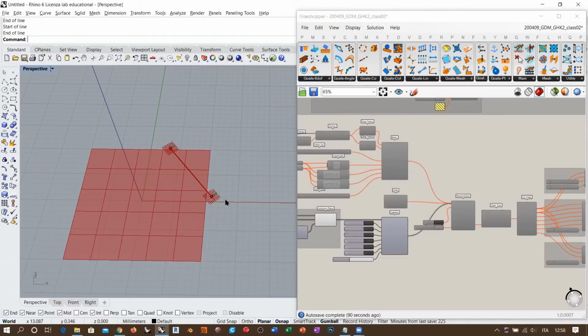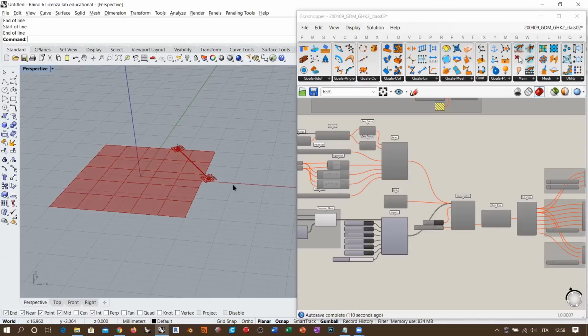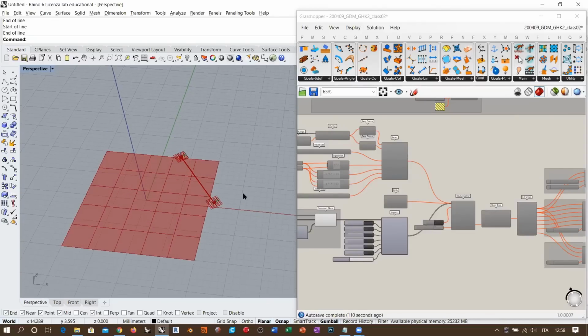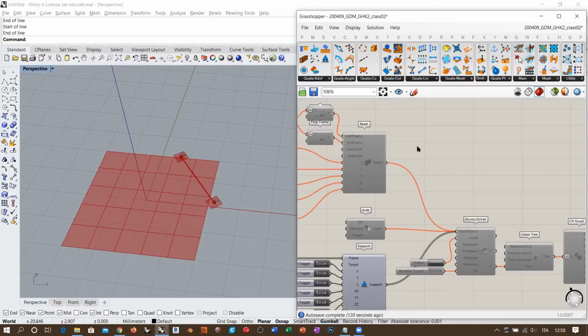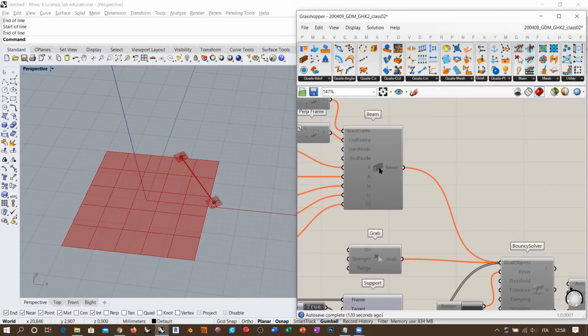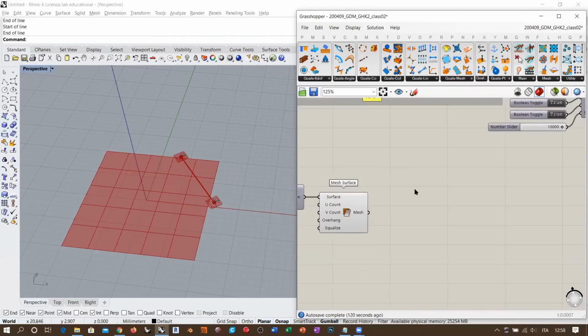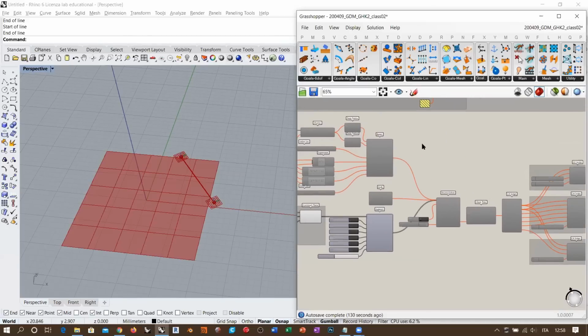We will see, for example, with the tensegrity, I will share with you one example that has a very complex tensegrity structure. The problem in that case was not programming the tensegrity behavior, but drawing the lines of the poles and of the elastic chords of the tensegrity system. So basically, it's not a question of whether it is possible or not. Of course, it is possible, but you have to understand what elements will be converted into beams or into elastic nets or whatever type of geometry you might want to use.